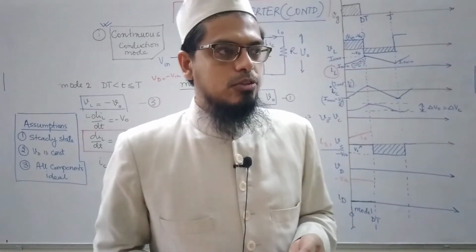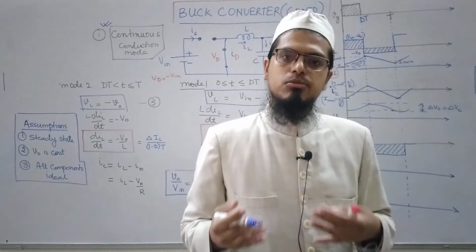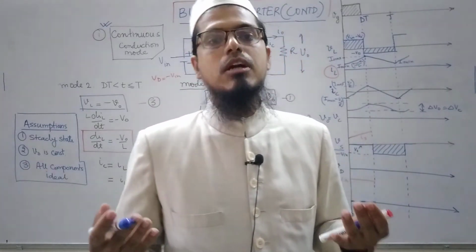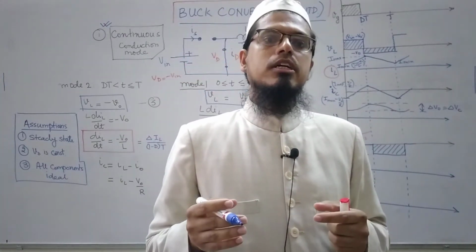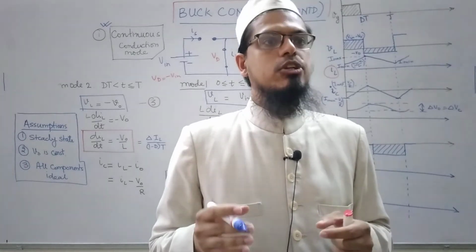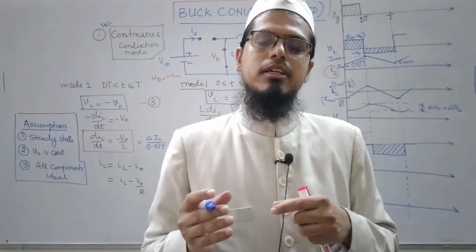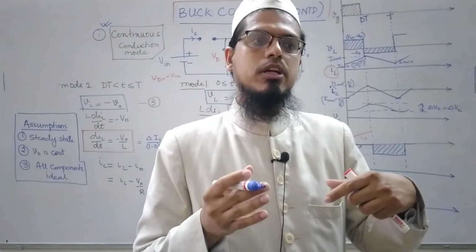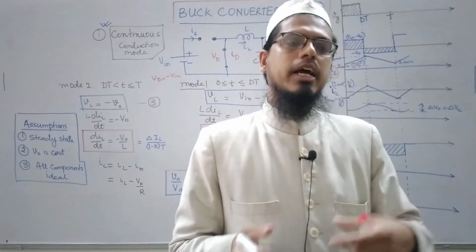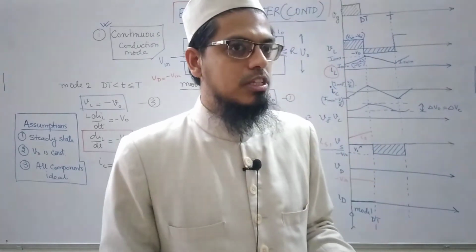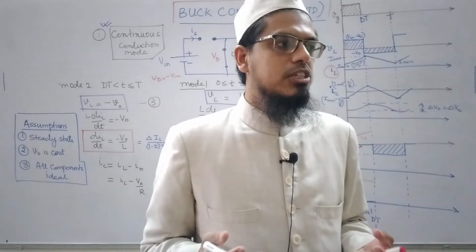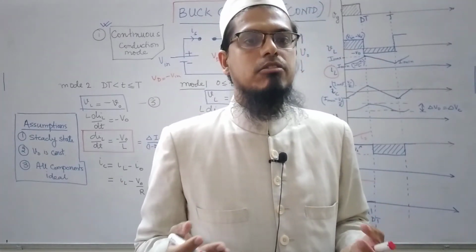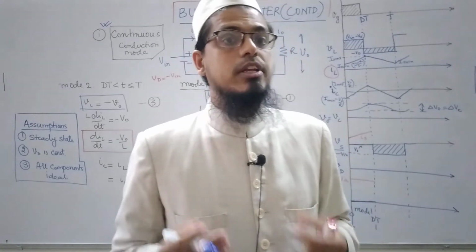Okay, so the lower the stress on the switch, the better is the converter, because it will lead to a converter in which you require a lesser rating of the device, and consequently lower cost and lesser loss. So these are the various features in a converter wherein the voltage stress is very less.